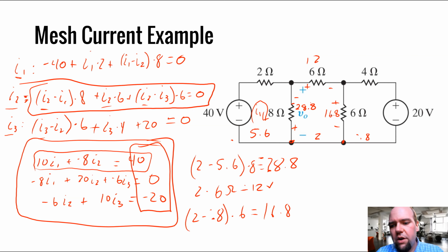We could check our work by going around one of these loops, going back to these equations, plugging in those values, making sure they actually equal 0. It's a good sanity check. My technique, if I'm doing a test or a quiz, is to go through it once, assume my math was right, leave a star for myself, and then go back and double check afterwards.